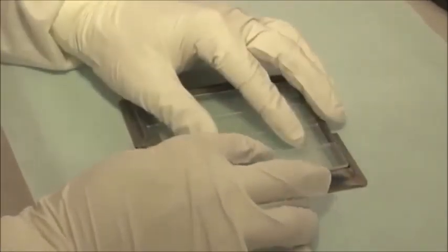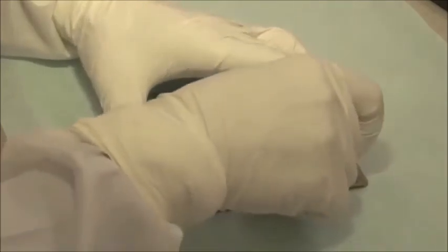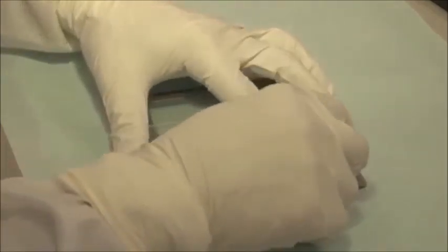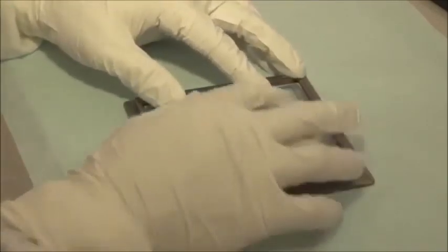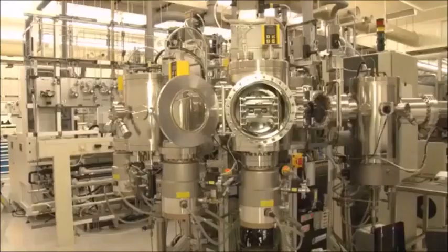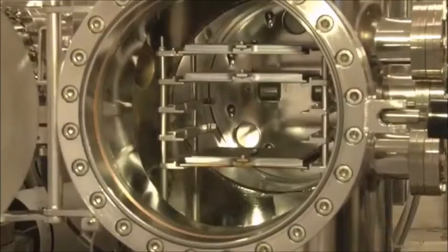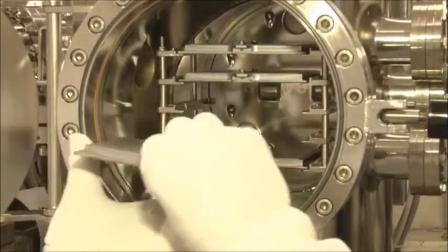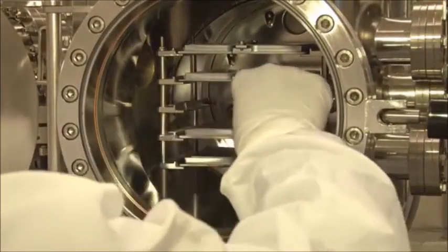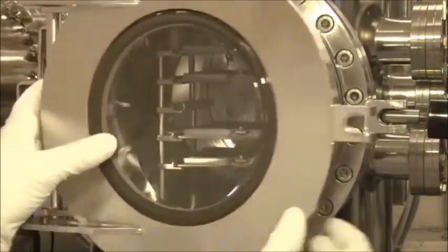This substrate holder is used during the plasma-enhanced chemical vapor deposition step to deposit the various thin silicon films. Again, we use a load lock. The load lock allows access to the various chambers. Every chamber is dedicated to deposit a type of silicon layer: P-type silicon carbide, intrinsic amorphous or nanocrystalline silicon, and N-doped amorphous silicon or N-doped nanocrystalline silicon.